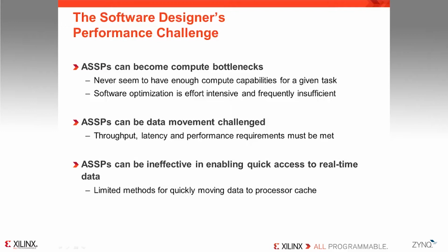In this session, we will address the common questions of how can I acquire data either through an external interface or via the Zynq XADC and quickly pass this data to the ARM processor in Zynq. How can I accelerate software DSP functions? Can I do it with the Neon instructions, which are single instruction multi-data? Can I go even faster by offloading software functions to programmable logic? And finally, how can I move data via DMA between the programmable logic and the processing system to accomplish the above tasks?